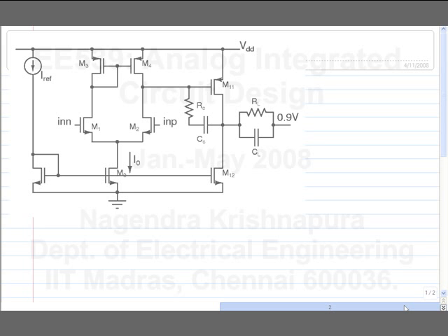Cascode where? So here. But that will reduce the output swing. Okay. So again, when you want to fix some biasing stuff, you should fix the bias branch, not the main functional part of it. It's not that you fix the functional part to suit your bias properly. You fix your bias properly so that it suits the functional part.